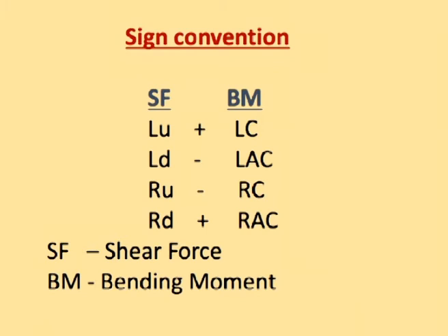In case of UDL, as I said, we will also have a uniformly distributed load. If it is a point load, it will have a line of action, and you will have the point about which moment is required. So, the distance between the line of action and the point we can easily take, but a uniformly distributed load is distributed over a length. So, we should see what is the total load first, and then the distance where the load is concentrated.